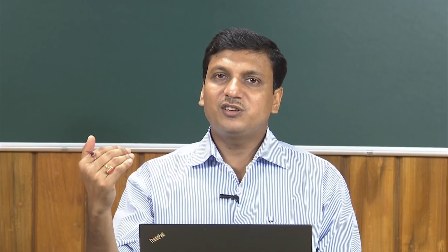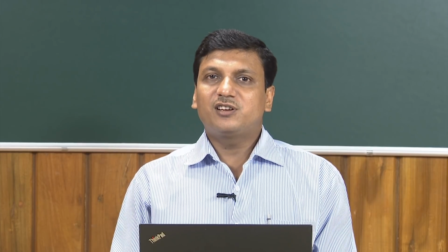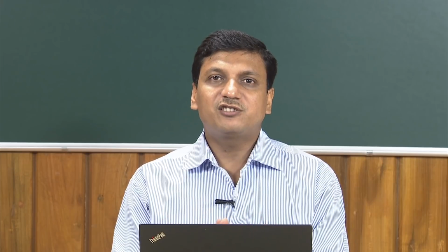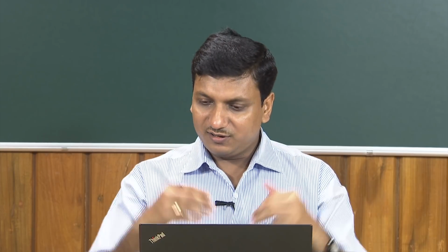Obviously we can get a temperature distribution which resembles the actual welding process more realistically. That means whatever physics we can find in the welding process, if we follow the numerical solution, the problem is more scientifically defined and more realistic with respect to what we observe in practice, than with any kind of analytical solution. But still the analytical solution is handy in the sense that we can quickly estimate the temperature distribution, and a rough estimation of the cooling rate is also possible using the analytical solution.